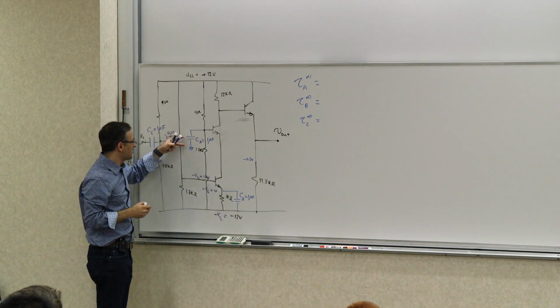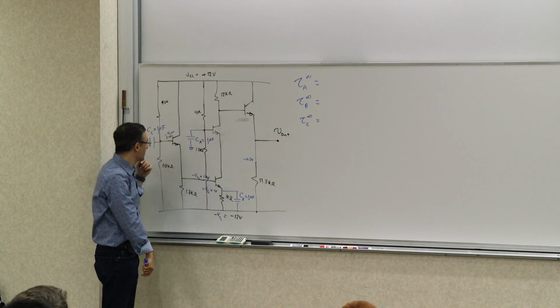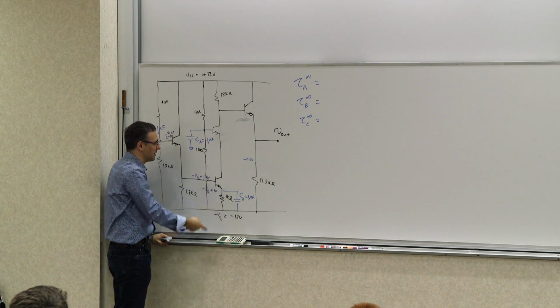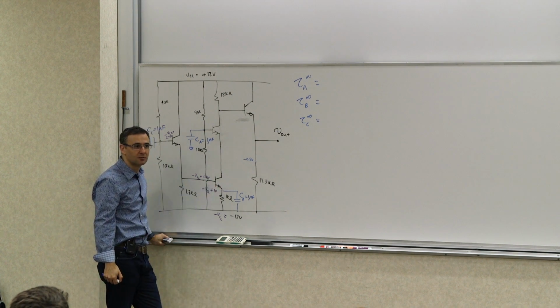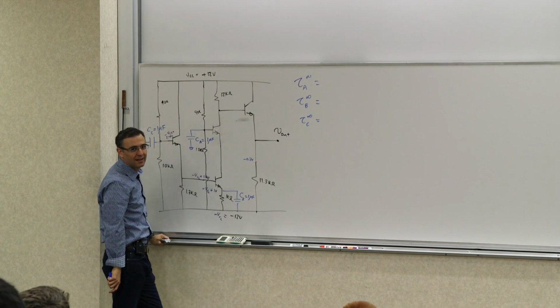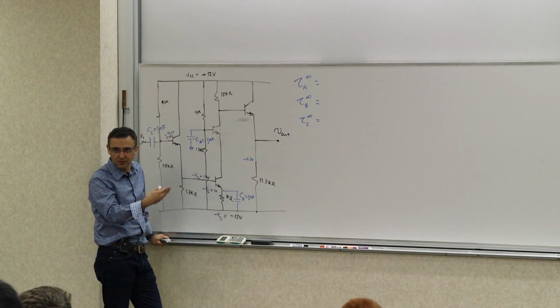Well, what is the resistance? So first of all, you have to infinite value everything else. So this is short-circuited, and this is short-circuited. So short-circuiting it basically makes this a common emitter with no degeneration. Right? What is the resistance seen looking into here? In this case, they are not affecting each other really that much. But if they were, you have to think about it.